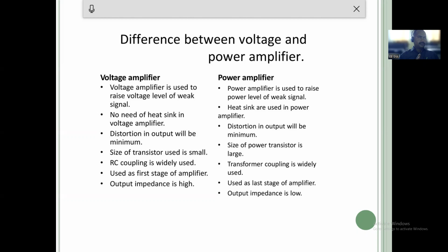So when we have to transfer maximum power from the input to the output, in that case source impedance should equal the load impedance, that is the condition, right? So if we use the transformer, right? A transformer has the same impedance at both input and output, right? That's why when a transformer is used for that purpose, meaning transformer coupling, for the purpose of a power amplifier, it gives the largest gain.